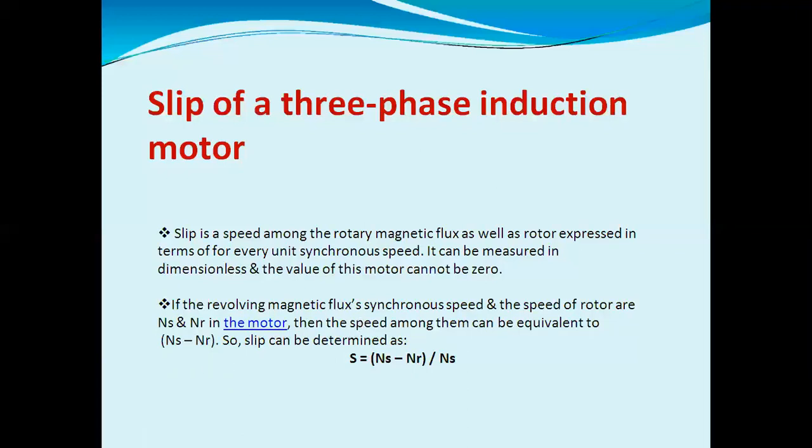So the slip can be expressed as S equal to Ns minus Nr by Ns. This is the general mathematical expression of slip, where S stands for slip.